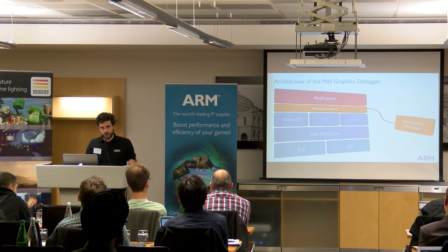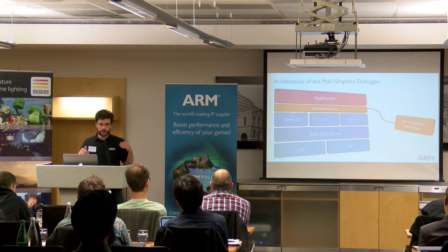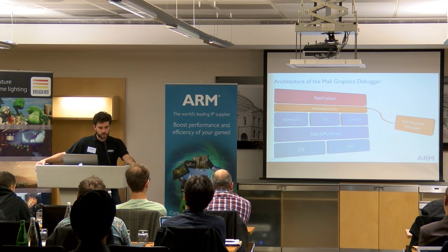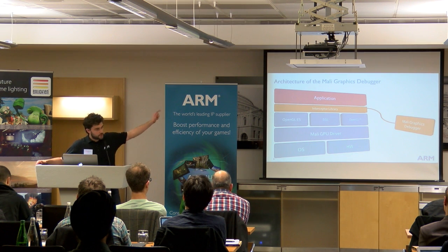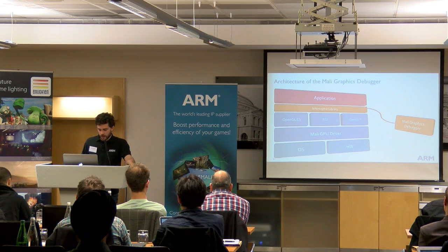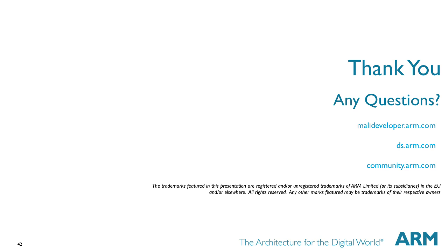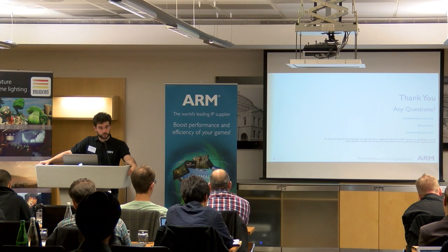This interceptor library is actually very lightweight if you're not capturing data. So it can stay on your system. It's basically just one additional function call every time you call a GL API. Once you enable the Mali graphics debugger, it will start transferring data. In that case, it can be heavyweight, depending on your application. So, as I said, I will cover both tools in detail after the break.